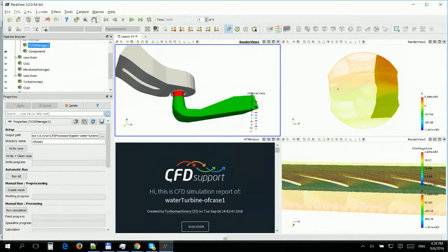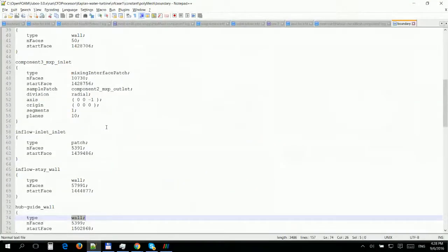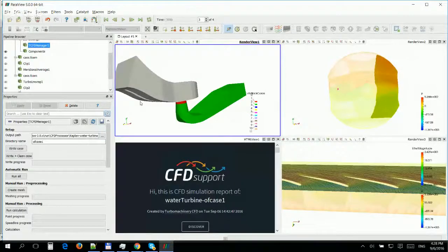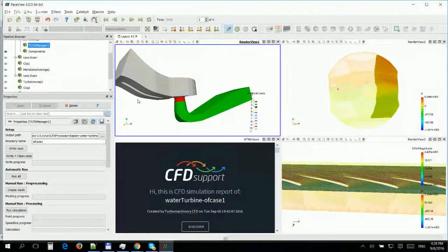Turbulence models, right? Currently, by default, we use wall functions with the k omega SST model. By default, we use k omega SST. Of course, it's OpenFOAM, so it's fully compatible with OpenFOAM.